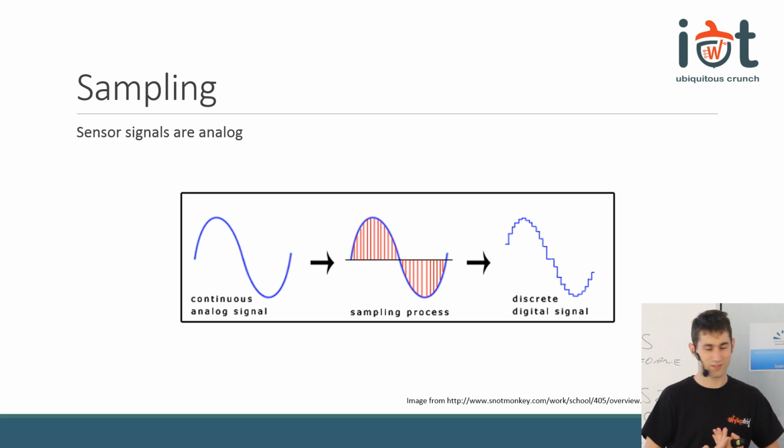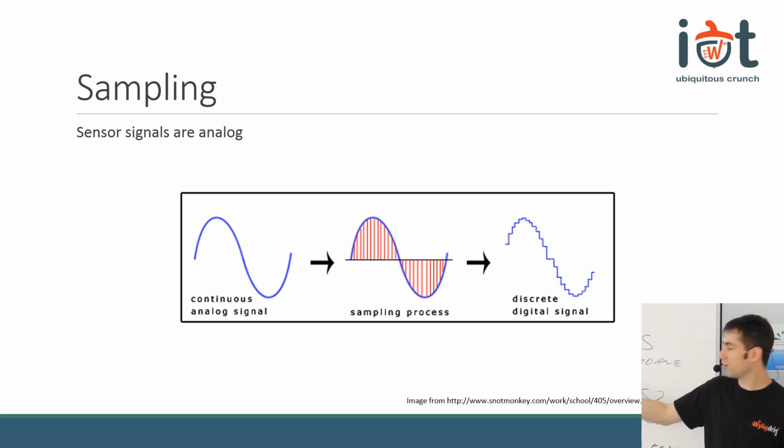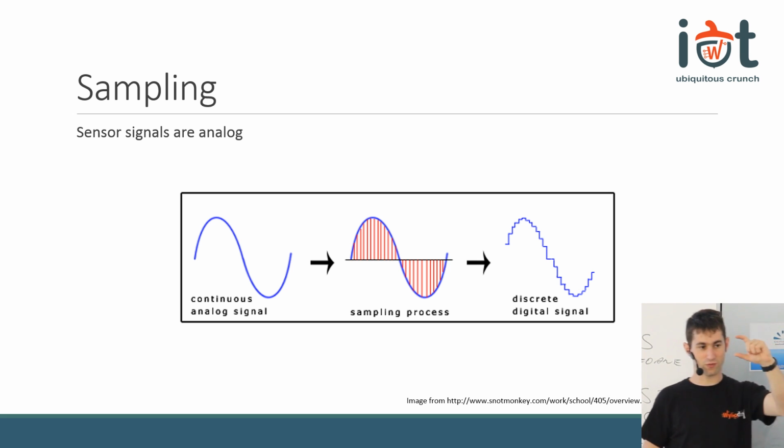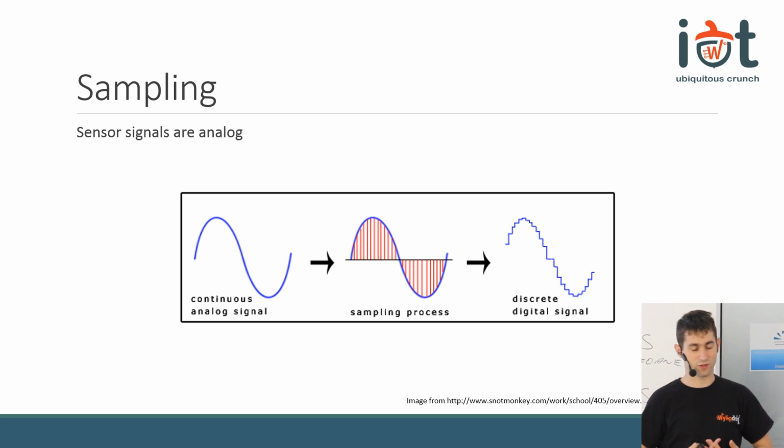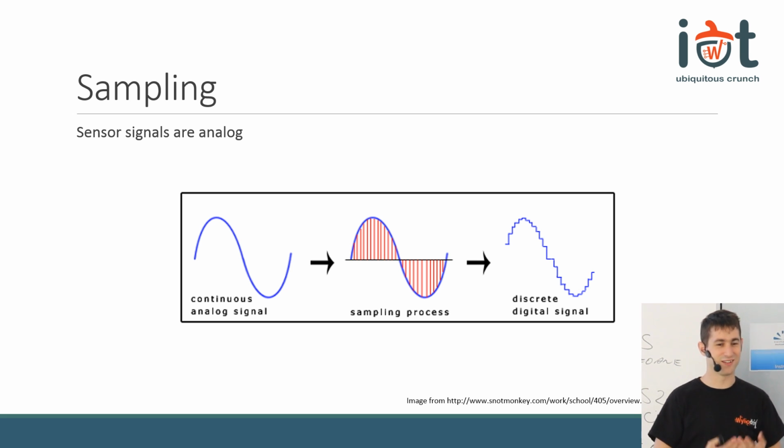Is it clear? So remember, the digital signal has steps. The horizontal step is the period, and we will assume a value over there because we did not measure it. The vertical value is due to the number of bits that we have. So if we have a device that can measure on 5 bits, there's only 32 different values for the signal.